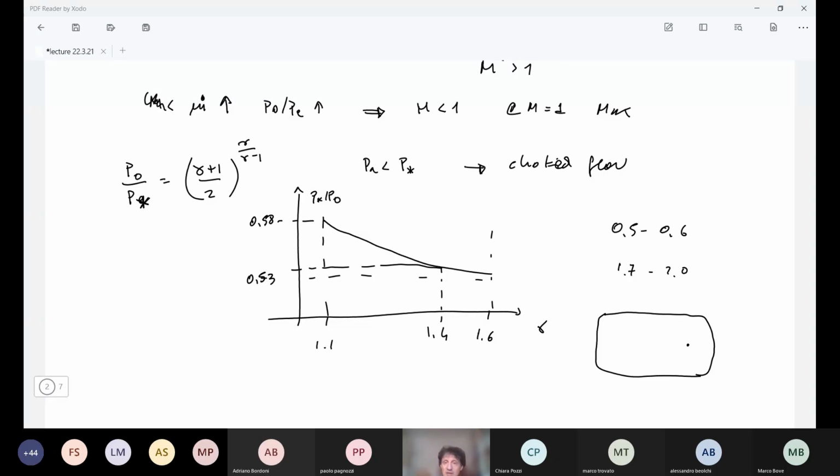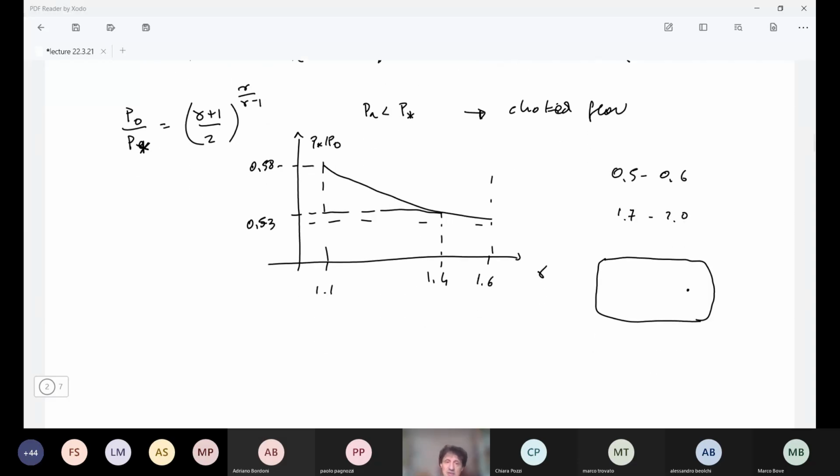Just the fact that we have this pressure difference tells us that if this pressure ratio is greater than 2, we will have choked flow. And so the mass flow rate will not be different if the pressure is 100 times lower than the enclosure pressure or 50 or anything else.